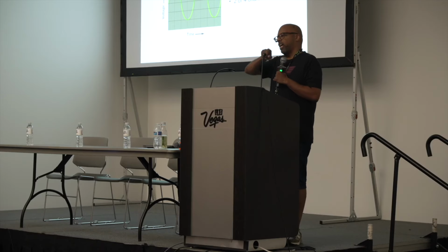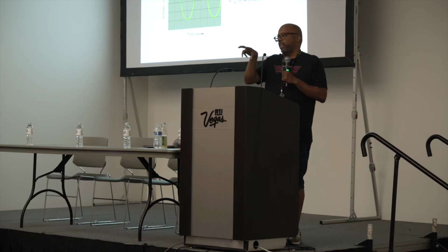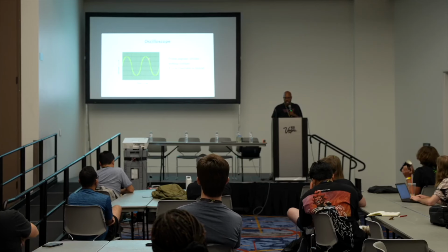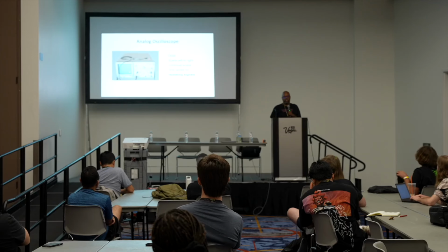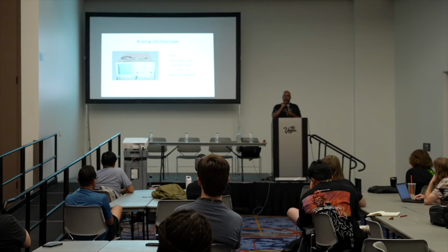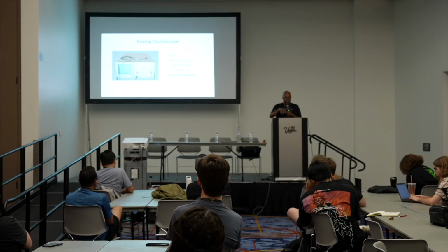So one thing you use is an oscilloscope. Now an oscilloscope, it'll have a screen and it just plots voltage over time, okay? Now oscilloscopes though, they usually have very few probes, 2 or 4 probes, so they can look at 2 wires at a time, or 4 wires at a time. And here's an old one, an old analog scope. Now the analog scopes, they only work for repeating signals. Okay, so the signal has to be the same over and over, like a waveform, a sine wave or something, and it'll work for that, right?